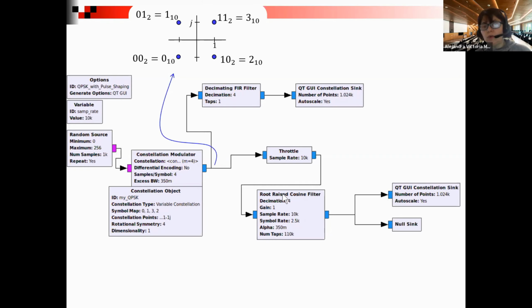At this point, we're going to see what happens when you differentiate. In one case, we're going to apply another root raised cosine filter. Therefore, the output of this should be raised cosine filter. At this point here, we have a pure raised cosine filter. Decimation by 4 means that the GRC is going to throw away, out of the 4 samples, 3 and just keep 1, the optimum one. This one is going to decimate by 4. And it's just going to be an identity filter. In other words, it's just sort of like multiplying the input by 1. It doesn't do anything else except decimate.